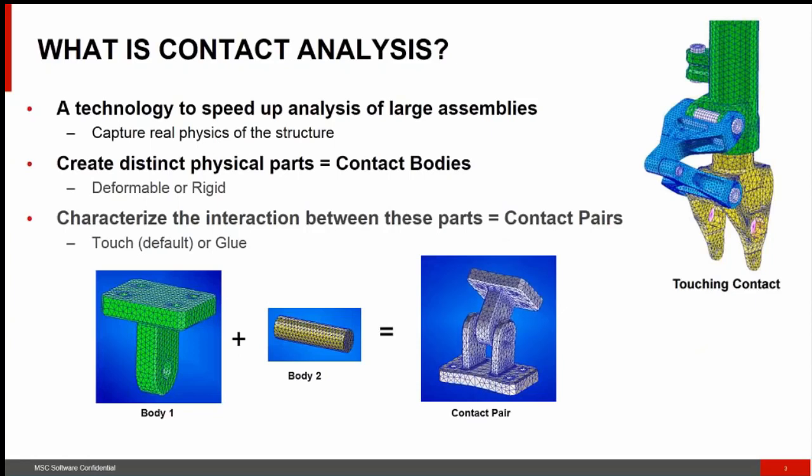And from the model assembly perspective, it's very important to have an integrated structure so the structure doesn't have any rigid body motions and the parts move properly. Many of the parts come from various sources or divisions and departments, and this is a challenge to assemble properly and quickly. So this is why the contact procedure can be very useful. This way we can detect the motion of these bodies and parts and easily assemble them without having to deal with node to node connections manually or remeshing the parts.